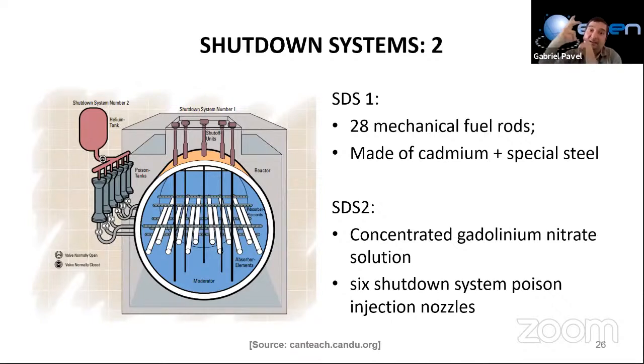So the electricity keeps these claws stuck to the shutdown rod. In case of losing the power, there is no force that keeps these rods. So automatically, due to gravity, these rods will drop into the reactor and will shut it down by cutting the fission reaction.